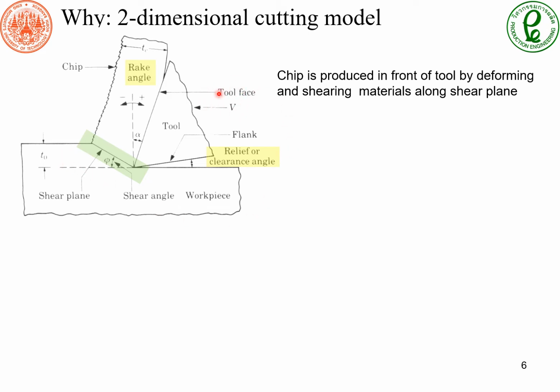Now, the cutting tool face has a slightly complex rotation. Usually the cutting tool is rotating and also providing some kind of feed rate, pushing, plowing into the workpiece. Here there is something called the shear plane. As the cutting tool is moving forward, the shear plane is moving forward, converting the work material from the left side, getting it to deform and become cutting chips on the other side. In this particular case, the cutting chip can flow all the way up and keep going. So this shear plane is actually providing the energy to remove the work material.